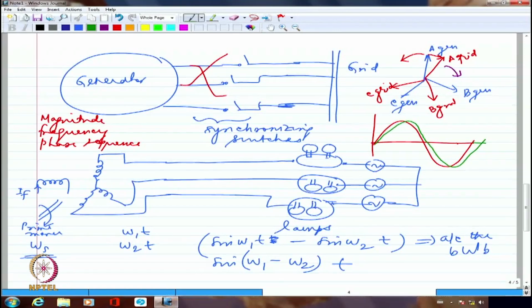So we are going to step it up. After stepping up, it is actually connected to the grid. So you can't afford to make a mistake there. You're talking about 700 and odd kV. So it's deadly if we try to connect it without proper synchronization. So for this, generally we use something called a synchroscope in the power station, which would check everything automatically and then connect it. Okay.